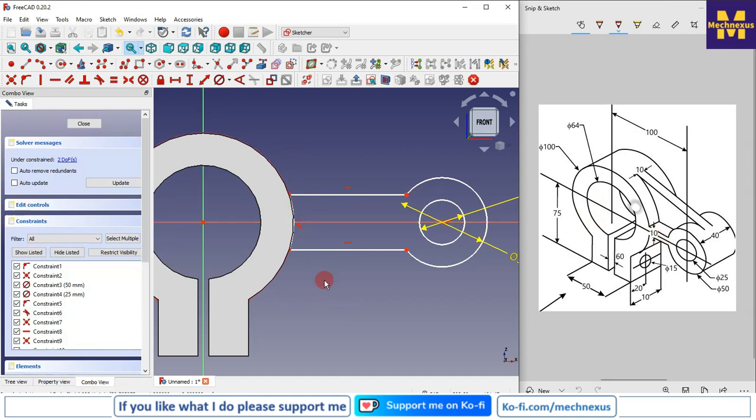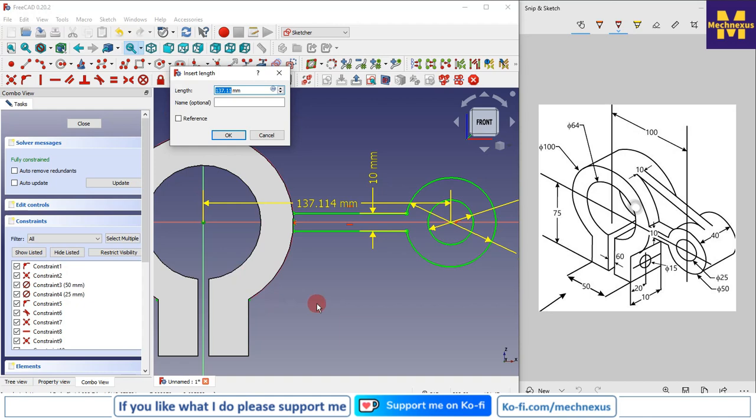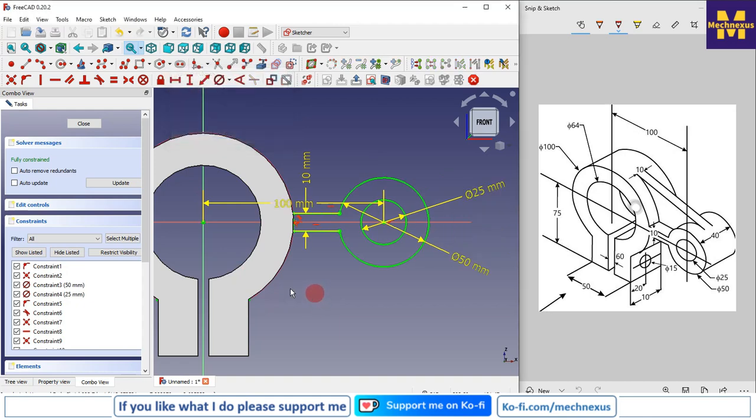Now this is the 10 mm, so I will select this point and this point with the 10 mm, and here the center to center distance is 100, so I will select this point and this point, the 100. So our profile is fully defined.